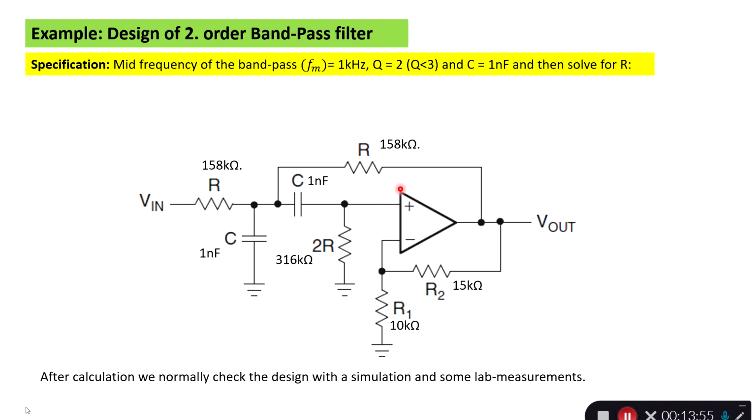That's always possible. When we have simulated, we also have to do a lab measurement, because when we go into the lab, a lot of parasitic elements around the real filter will show up, and then we have to deal with it there. Going physical, typical filters have to be on a circuit board with very short wires and an appropriate power supply.